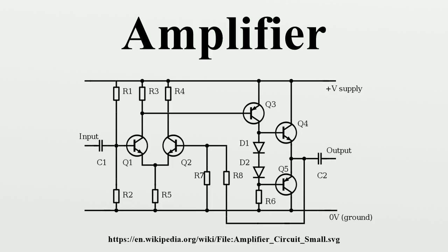Low distortion. All amplifiers and transducers distort to some extent. They cannot be perfectly linear, but aim to pass signals without affecting the harmonic content of the sound more than the human ear can tolerate. That tolerance of distortion, and indeed the possibility that some warmth or second harmonic distortion improves the musicality of the sound, are subjects of great debate.